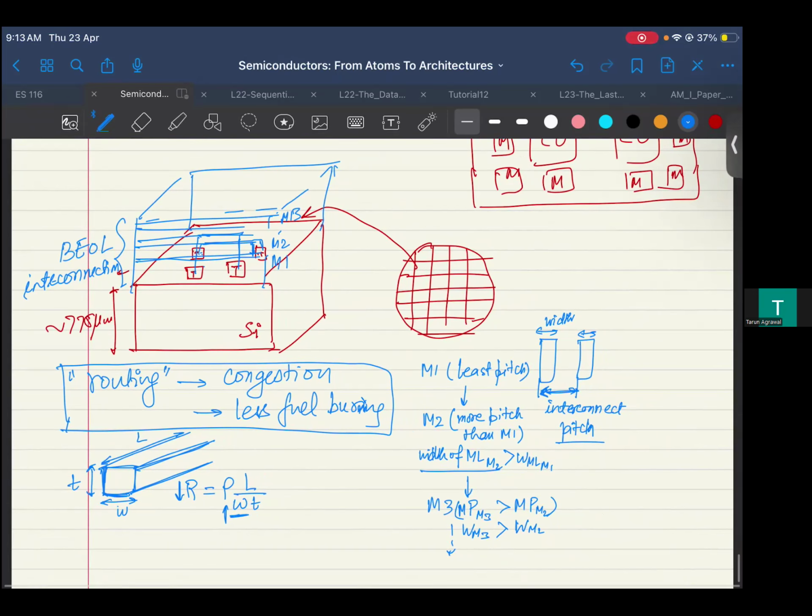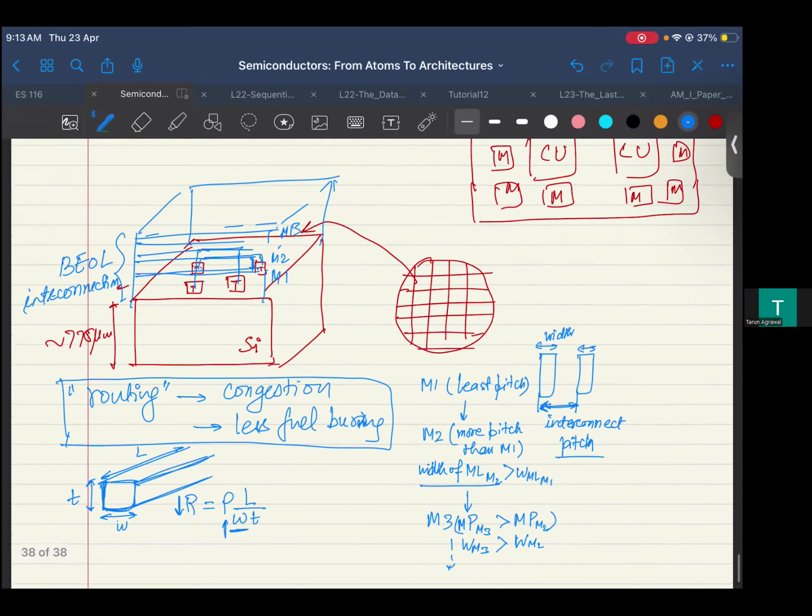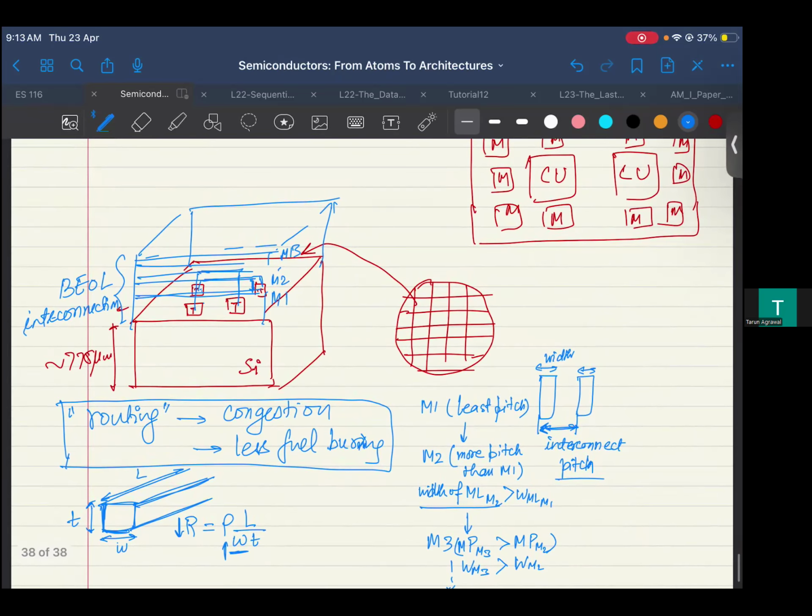Okay, coming back to our picture. With the interconnections, we see clearly that this is much more complex than what you can imagine. With this congestion and everything, there are many, many metal lines in this back end of line, which we saw is 13 metal layers. So the sheer volume of transistors, or the devices you are trying to connect, is just huge.